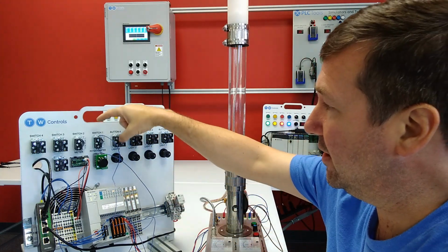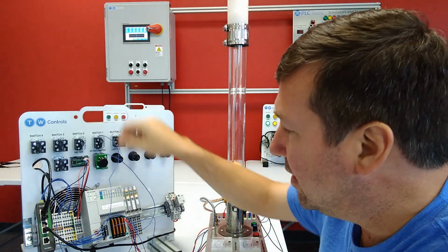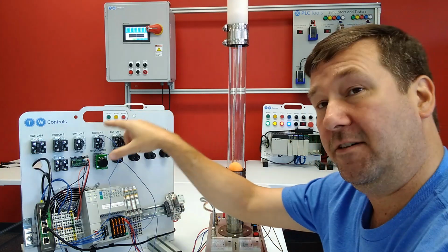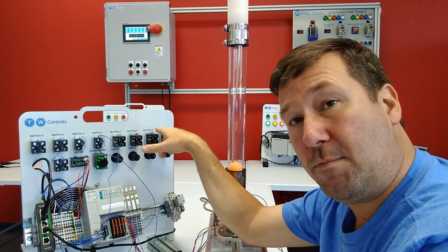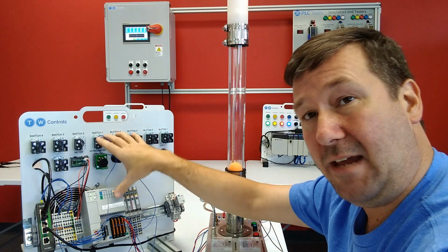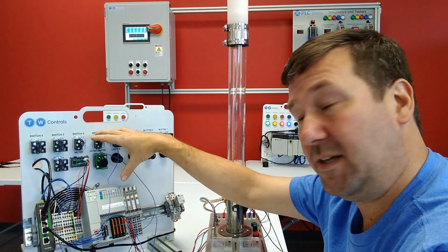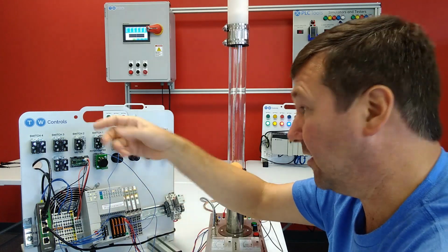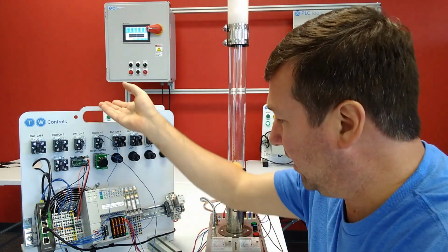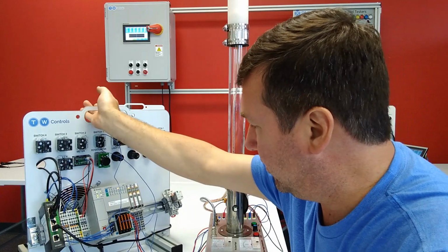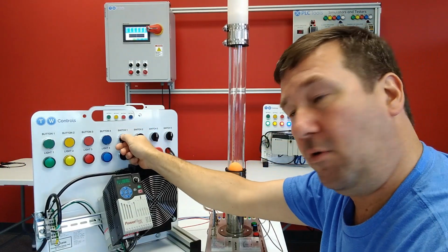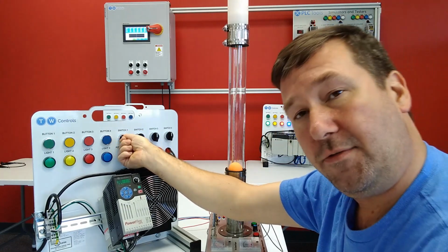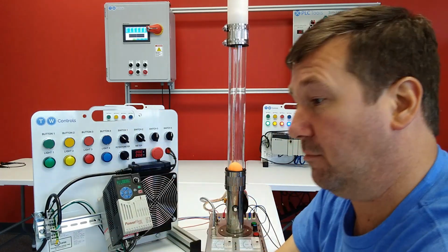So what I have done is I've wired switch 1 to input 4 of the CompactLogix PLC. Now, if you still have yours wired per the getting started guide that came with the trainer, then it's going to be the one. But we have videos on how to do that. So if you have any questions, just look down in the comments. But that's already wired like that. So we're going to spin the trainer around. And we're going to make it where when switch 1 is on or to the right, it'll be on auto mode. And if it's off and to the left, it will be in manual mode.